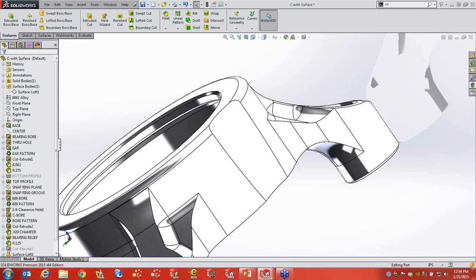But in a case like that where the indented shape is smaller than the tool that you're using, you may be able to just scale the tool using the scale feature. That might be one way. Yeah, I'd have to look at what kind of geometry you're trying to create with that. But negative numbers do not work. Oh, to leave material for hand fitting. Yeah, negative number does not work.